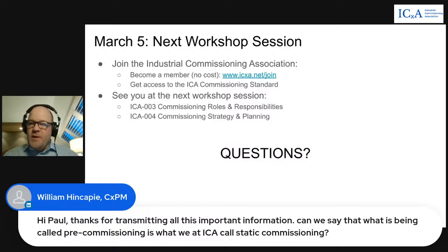Thanks for transmitting all this important information. Can we say that what is being called pre-commissioning is what we at ICA call static commissioning? That is correct. If you look into ICA 002 and the legacy terminology section, when we're putting pre-commissioning to rest, that's essentially what it's being replaced with: static commissioning, a very specific, discrete stage of the commissioning process that doesn't get blurred between construction's pre-commissioning activities or what some of the other vendors call pre-commissioning.